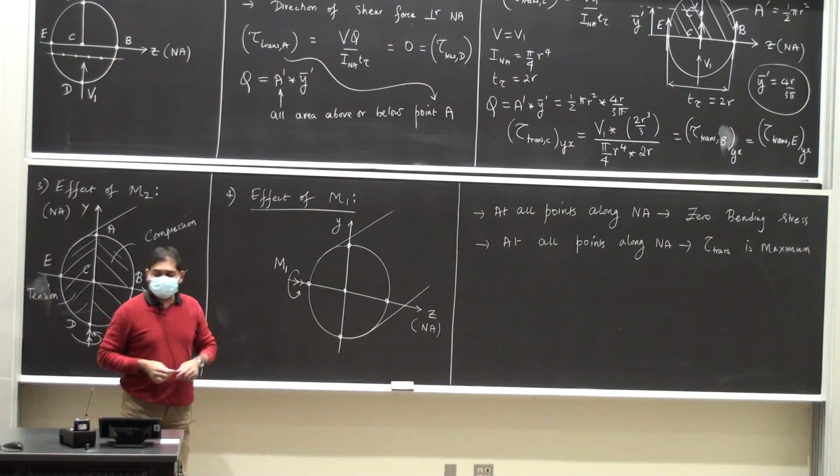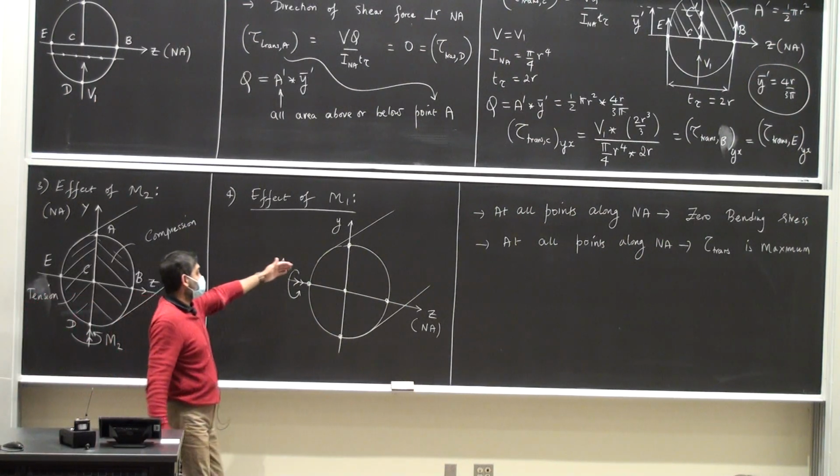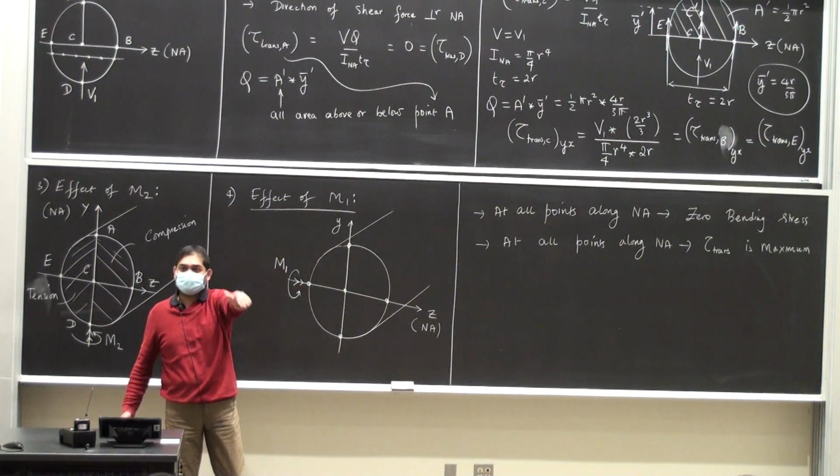Alright, so if I look at this, here is the example. My arm here outstretched is the z-axis. The moment is acting such that if I curl my fingers, my thumb is pointed along my left arm here. So I'm going to take this and rotate it this way. This was originally straight. I take the screen, rotate it, which means that all the fibers on the top are getting pulled out.